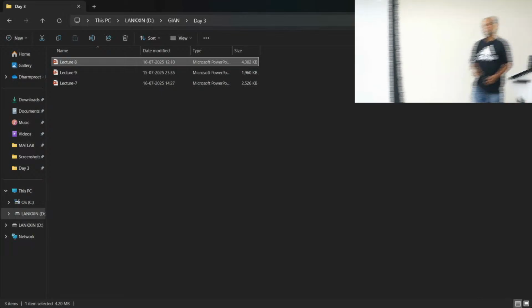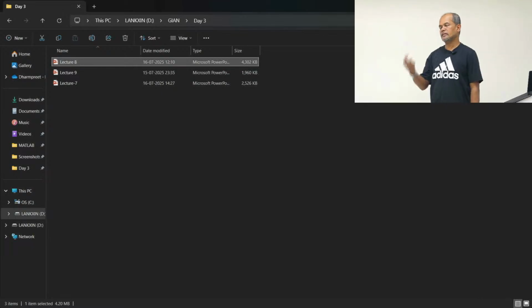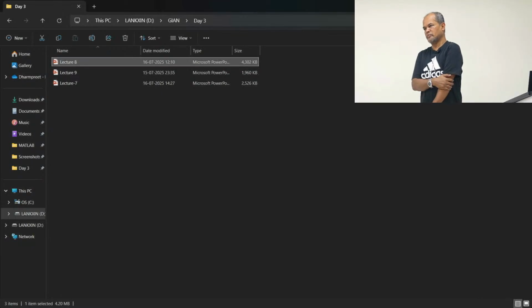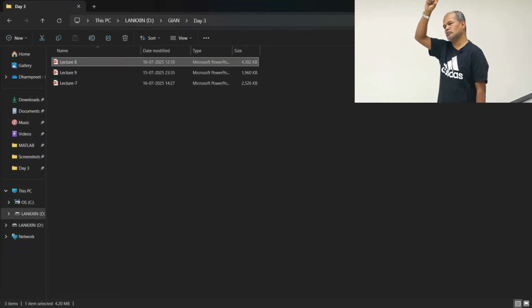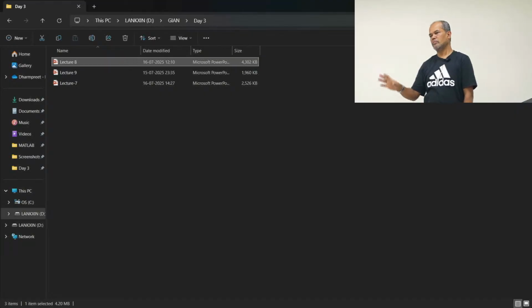For voltage, in different countries, there are many different requirements. In Australia, for low voltage grid, we have, I think, plus minus 5%. For India, I'm not sure, but it should be close. In high voltage, sometimes they consider plus minus 10%, but for low voltage distribution grid it is plus minus 5%.